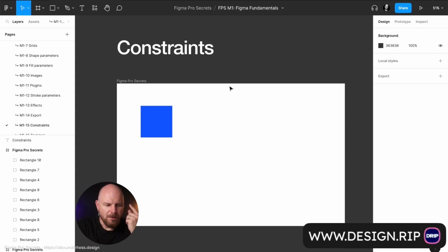will allow you to add just one additional thing as a parameter to the shape or text inside of the frame, and it will completely change the behavior of this frame when the frame changes size. This is specifically useful when you're creating, for example, responsive designs, responsive mobile screens, responsive websites, or you want to create a card where the element inside of the card will change its position when the size of the image changes. How does it work? Let me show you an example.